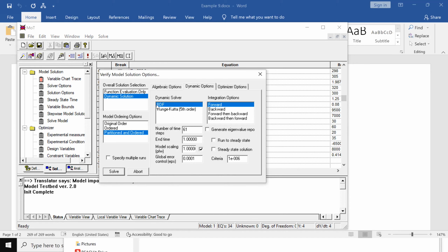By default, we can take the forward integration and we can change the time scale to 0.02. And we can say what should be the end time, 1.5. Then it automatically calculates that if the time scale is 0.02 and we want to end, it will need 357 integration steps. And these are not fixed step size, it is variable step size. So we have defined all of these. Now we are ready to run the problem.